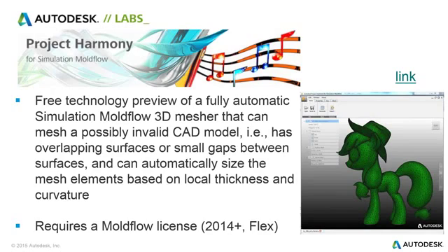In this particular case, you find areas that are flattish, and there the mesh size will be significantly coarser, because it can be coarser over there. In areas that are very detailed, or where you see a big transition in thickness, for instance, or related features, we will refine the element size automatically.